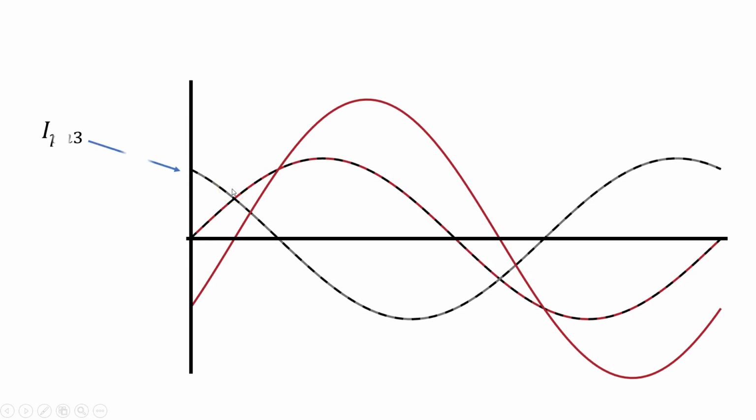And just for an illustration, we have phase 3 current here, which is a combination of the phasor of the black and the grey phases. And we've got phase 1, which is a combination of the brown and the black line current. And we have line 1 current. So at each point along the time axis here, we're going to subtract phase 3 from phase 1.